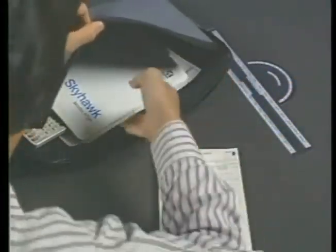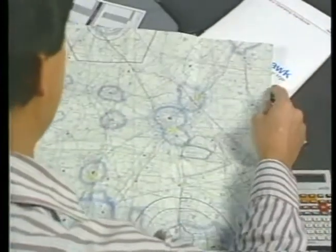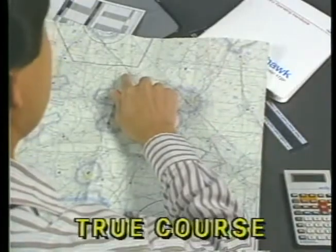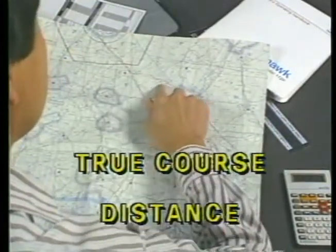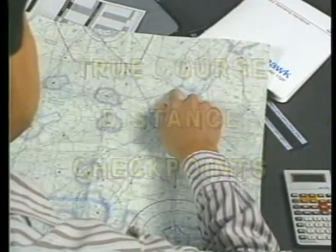As with pilotage, preparation for dead reckoning navigation begins prior to flight, when you use time, speed, distance, and direction to predict the movement of your aircraft along the planned route. Thorough pre-flight planning is the key to a successful cross-country flight. You'll usually begin with an analysis of the route. In this step, you'll determine the true course, measure the distance, and select prominent checkpoints.